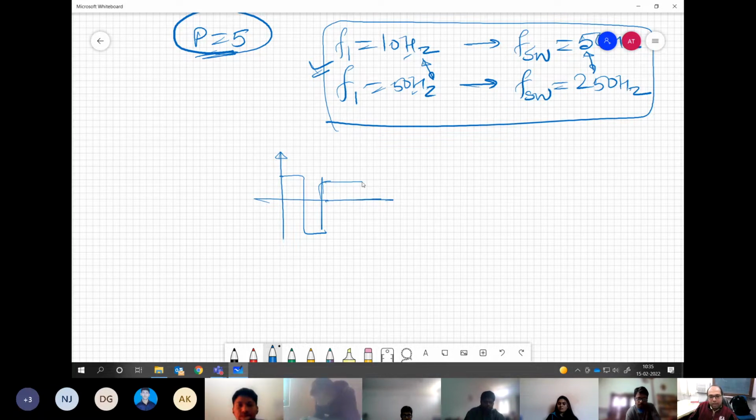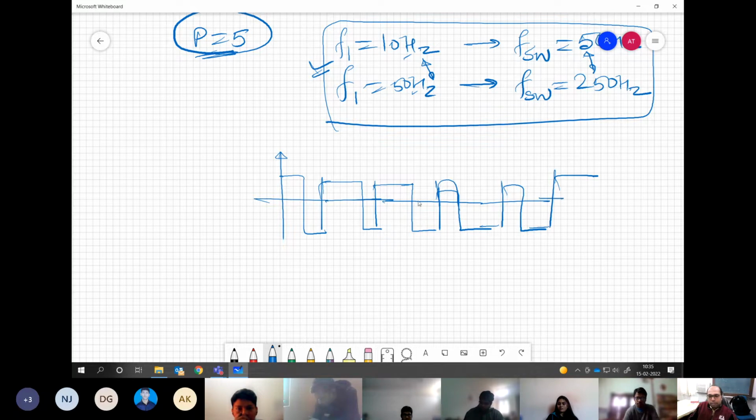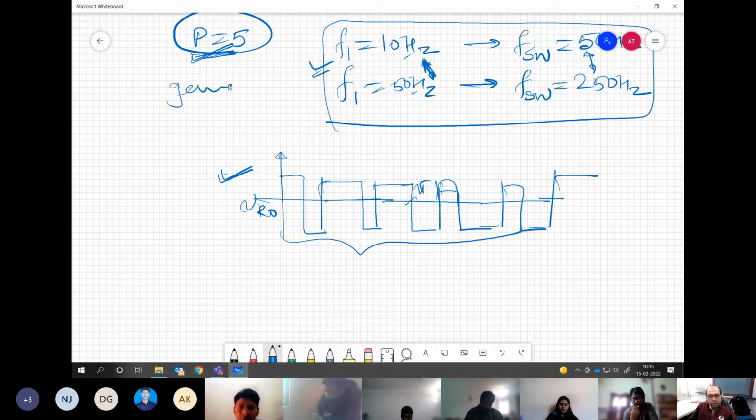One notch in one quarter cycle, and so this is going to be the nature of PWM for the entire operation, which means more or less we have decided what quality we are going to get from the system, irrespective of the fundamental frequency and switching frequency here, because we have fixed the pulse number. So that is how this is a generic term which can tell a lot of things about the property of how your waveform, or the quality of the output current, is going to be.